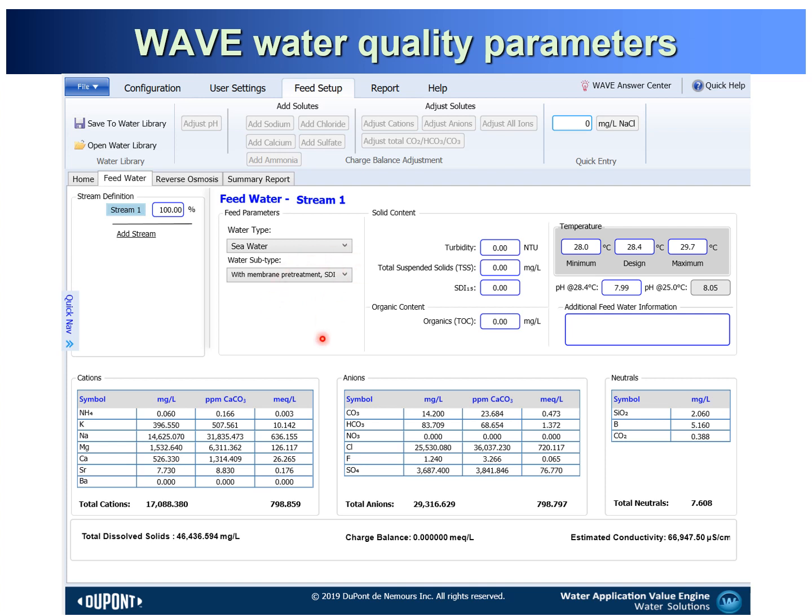This will provide all your water chemistry when you recover your seawater more than 50%, and what kind of inorganic scaling and organic scaling, biofouling scaling can be predicted from this software. That's what it is. You don't need a very strong water chemistry background, because this software will tell you briefly what kind of potential there is for your membrane fouling. So we will study in more detail how to design with this WAVE software.